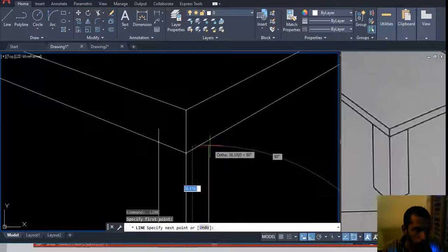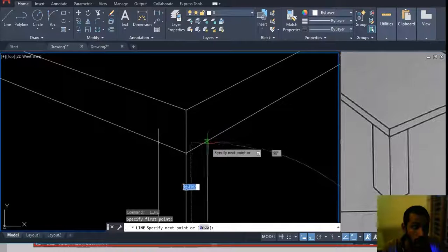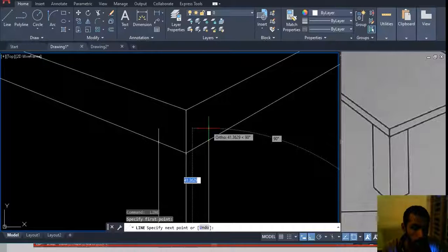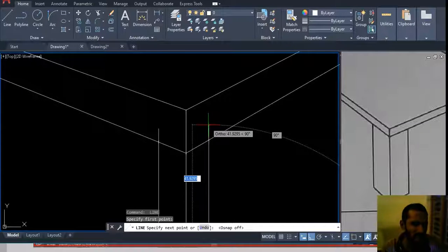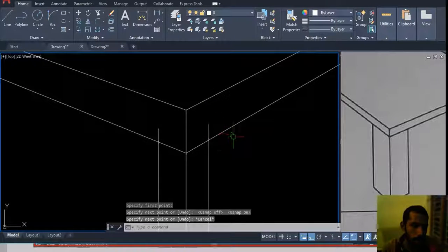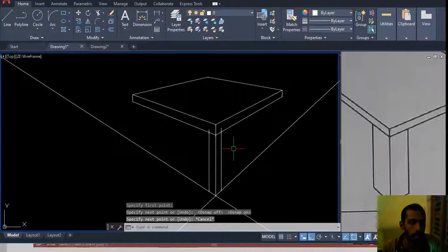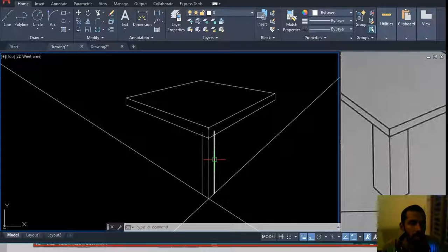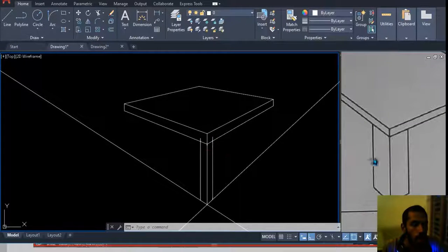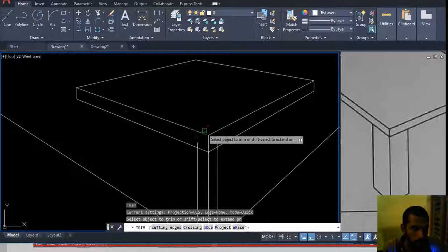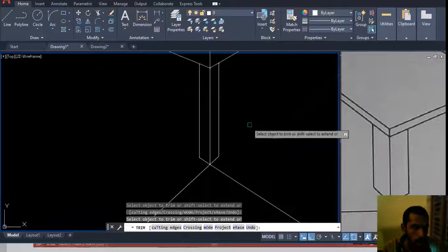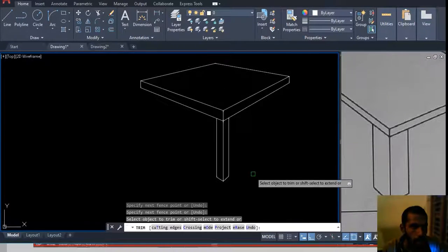It's not possible for me to pick a point right on top of this line, as everything is showing nearest. So I would like to either disable the object snap and click it. That might be very crazy to extend it, so I'll turn on no snap and click on top of this line. Then it's possible to trim this line when you're trimming all the others. Okay, that's great. Alright, what happens next is you can trim these lines right here, and here. What else do you want?